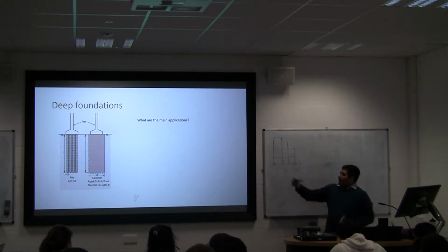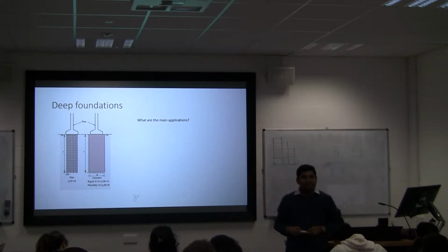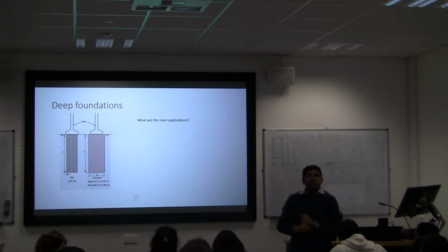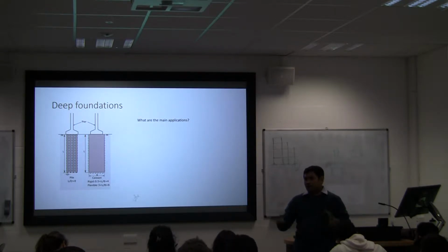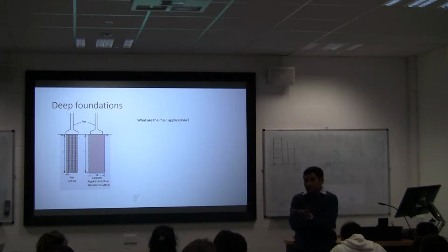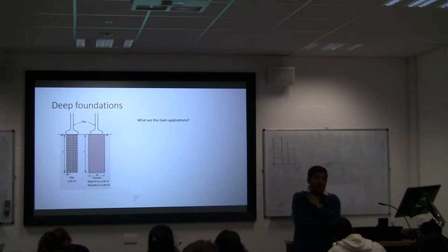Okay, now, what are the applications of these? Where do you need pile foundations? Some examples. Where you would definitely need pile foundations, so that there's no other way. Bridges? Yeah, maybe a major bridge, like a cable-stayed bridge, a large span bridge. You can't avoid it. You have to have it. Yeah, the highest buildings. In most places you have to have it. Offshore applications, yes. So that there's no other way to do it, right?